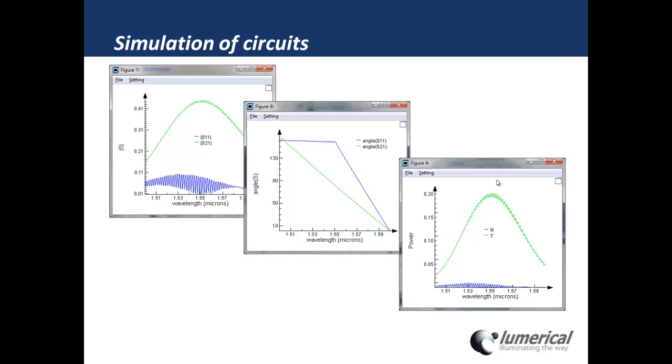In terms of the power, this is the curve that I showed you. I've just relabeled the axes and plotted as a function of wavelength. Here we see the reflection and the transmission. So we can see already that these reflections, which in terms of power from the grating coupler are relatively low, on the percent or less, do have some important consequences. Even on the transmission side, we're seeing the effect of all these ripples.